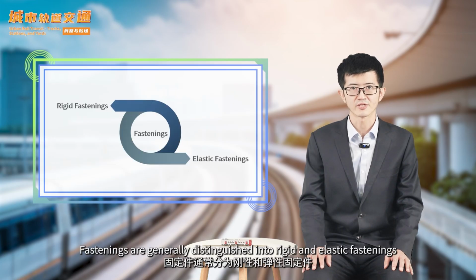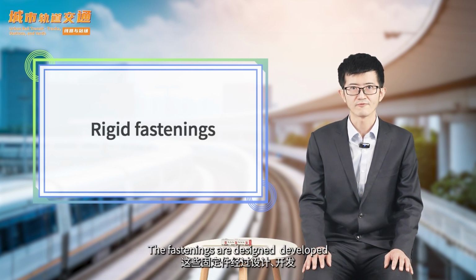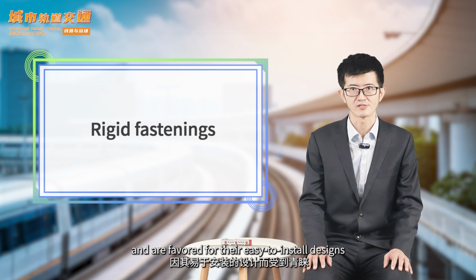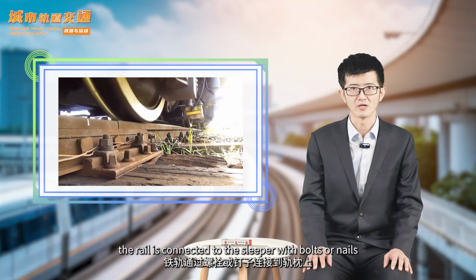Fastenings are generally distinguished into rigid and elastic fastenings, and let's delve into the concept of the rigid fastenings first. Rigid fastenings are used with timber or steel sleepers. The fastenings are designed, developed, and field-proven under extreme weather conditions and are favored for their easy-to-install designs. In rigid fastenings, the rail is connected to the sleeper with bolts or nails.